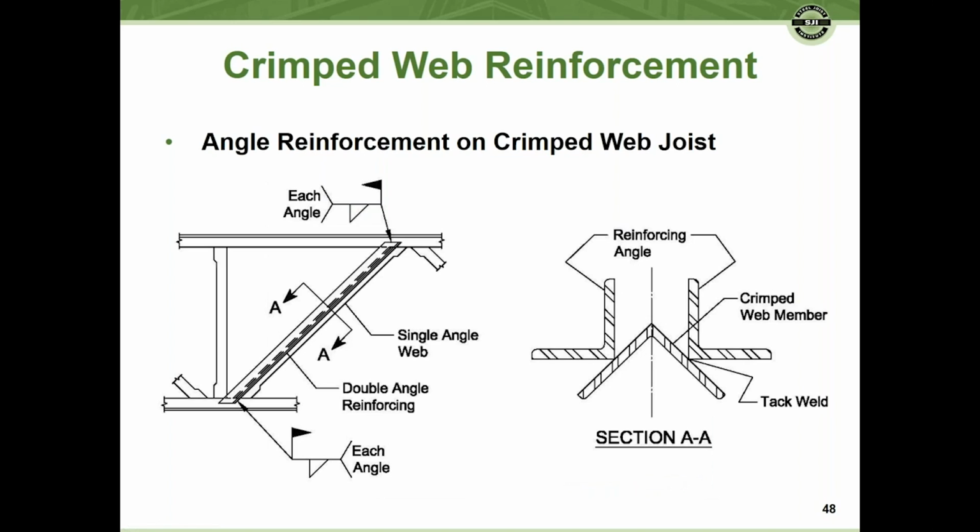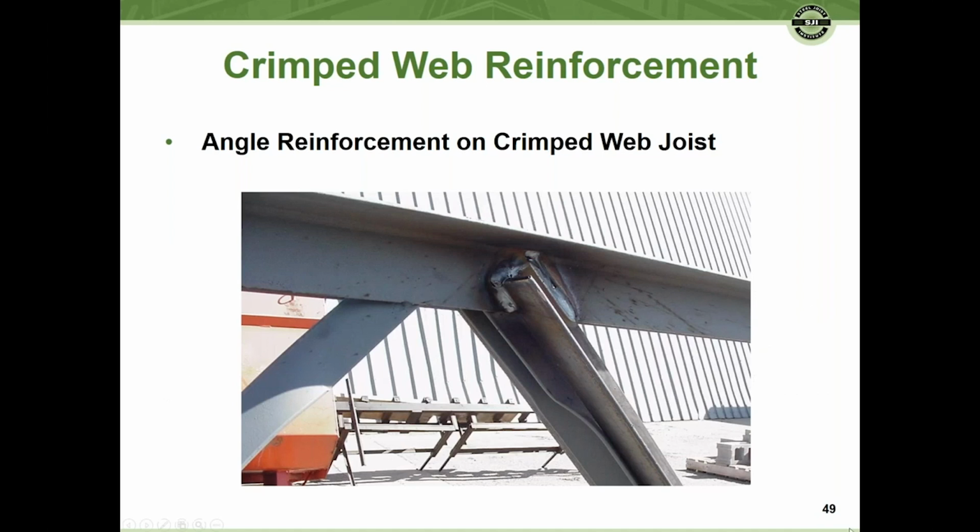There again, here we've got some typical details that you might think of, and please note that in not all cases do you need to cope the ends of the reinforcing web, but in a lot of cases it is going to be required, and that helps you get better fit up and get more weld where you want it to be.